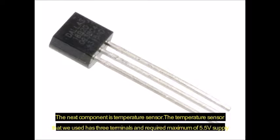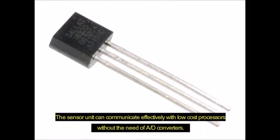The next component is the temperature sensor. The temperature sensor that we use has 3 terminals and requires a maximum of 5.5 volt supply. Temperature sensors are directly connected to the microprocessor input and thus capable of direct and reliable communication with microprocessors. The sensor unit can communicate effectively with low-cost processors without the need of AD converters.